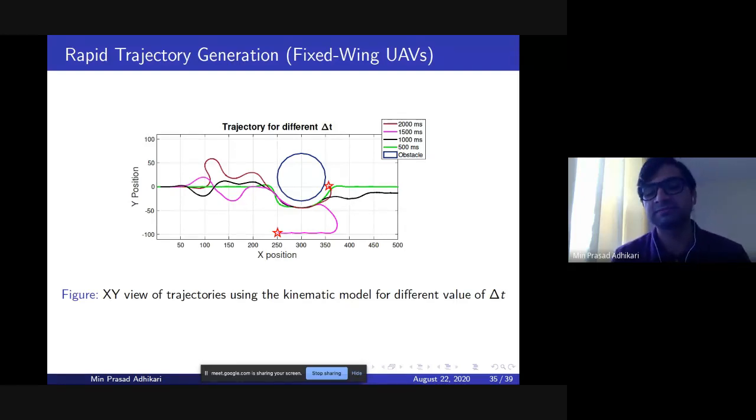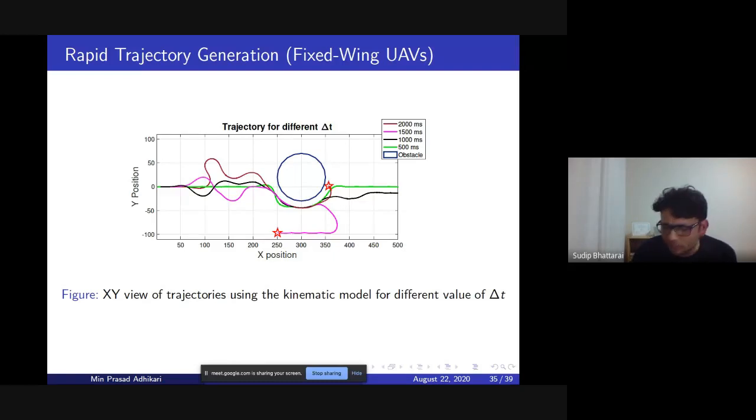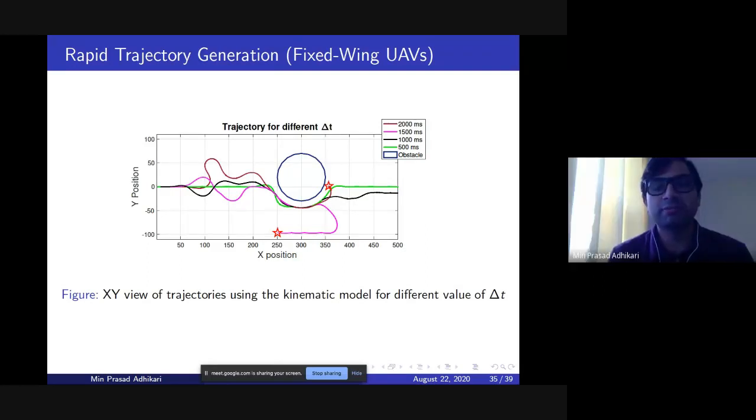So what is the trade-off for having the smallest possible delta t? What would keep you from doing that? It's the computation capability on board and the size of the problem. Everything combines here. If you have good computation capability on board, maybe a TX2 or better computers, then you might be able to solve up to a 12 second horizon with 200 millisecond sampling time.